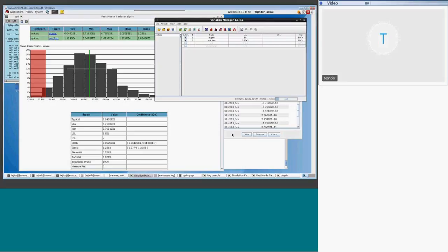Yes. Okay, so the terminology of local variation: different people use different types of terminology. They use mismatching for it. It's to be distinguished from global and local variations. So your global is the process variation. Your local is mismatch between devices.